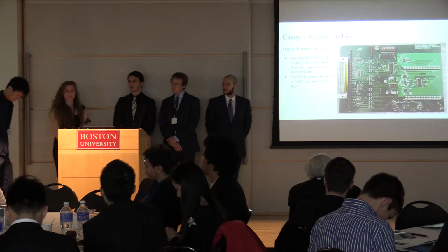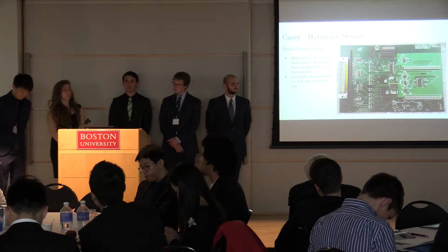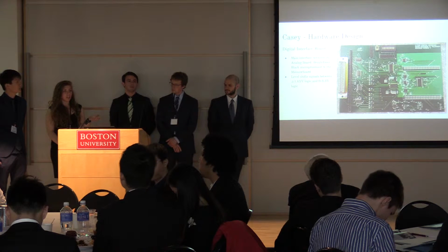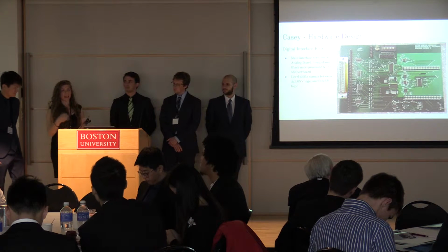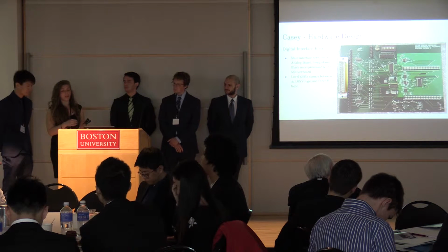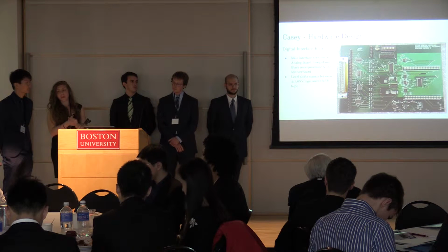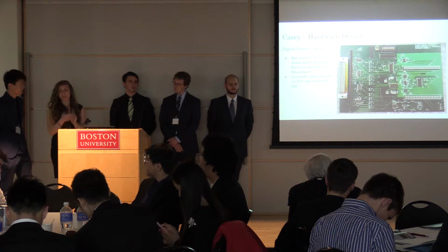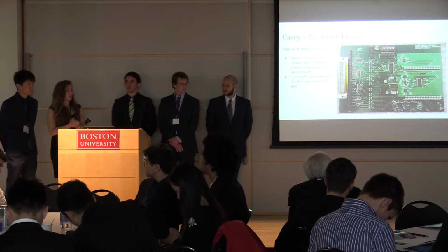So my main responsibility for this project was to design the digital interface board. The interface board interfaces the analog PCB that Neil designed and the BeagleBone Black, as well as the BeagleBone Black and the Miniboard Max. The main functionality of my board is just level shifting. It level shifts from the plus minus 1.6 logic supplied from the analog board to the 3.3 logic on the microprocessor.